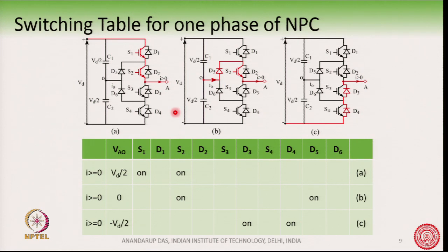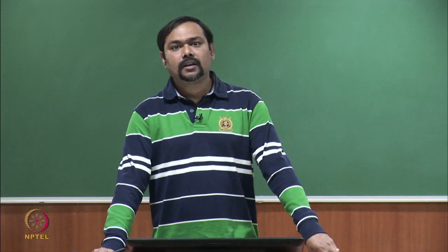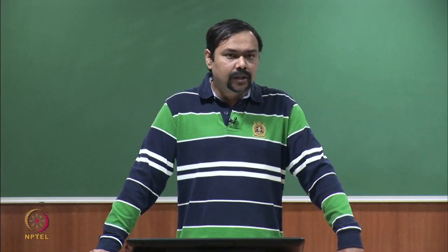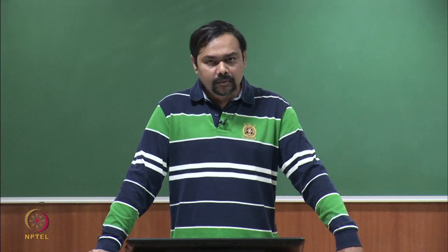Another thing that I forgot to mention previously is where we use neutral point clamp converters, because as I was discussing the IGBTs, it came to mind. The neutral point clamp converter is a multi-level converter typically used in the kilovolt range and the hundreds of kilowatts to megawatt power range. 11 kilovolt is possible, but probably not at high voltage DC transmission.